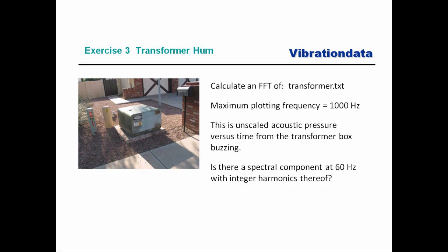So then this low current, high voltage power is sent into your neighborhoods or near your office, wherever you might work, or the stores that you may shop at. And there's another transformer. So I'll call the one at the power plant the step-up transformer. I'll call this one near your home the step-down transformer. And what it does is it's going to reduce the voltage and increase the current. And it does that because that's more efficient for powering your air conditioning unit and your refrigerator, all of your appliances, your lighting, whatever. So that's probably an oversimplified explanation of how power gets transmitted.